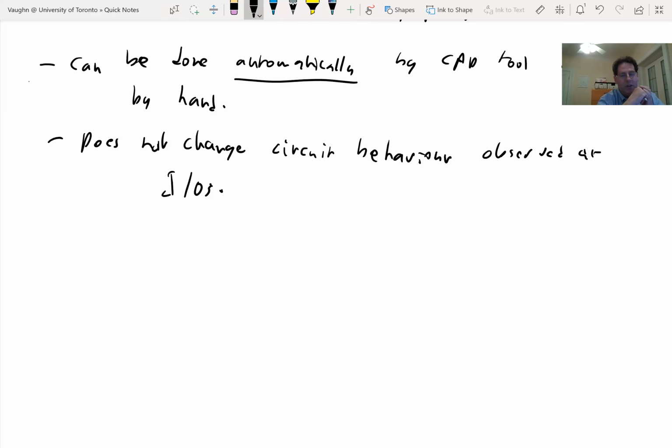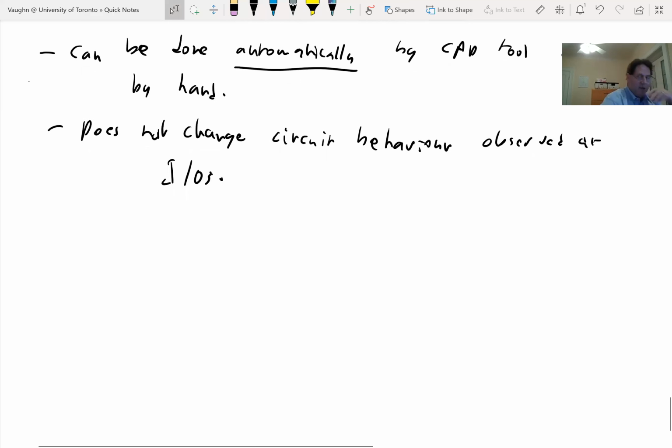And so you need to find a tool that supports it when you give it detailed constraints saying, I'm telling you it's okay here. But retiming, as I said, because it's not observable outside, can be done automatically. Now, many CAD tools still don't do retiming automatically. You'll have to turn it on. So by default, they won't turn it on.